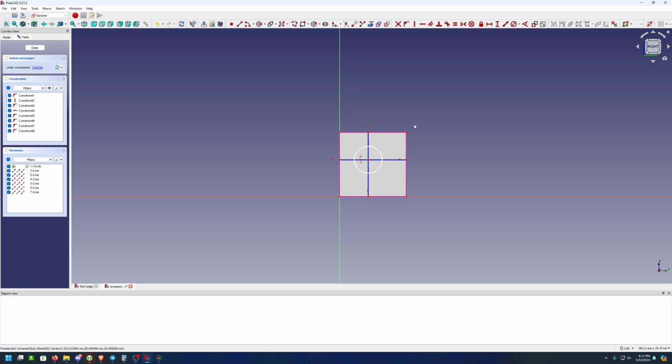I was just kind of guessing. I was like, okay, well, this looks like I'm against this line. And it's just not the right way of doing it. Honestly, if you're doing it right, your sketch will be fully constrained, unless there's a really good reason not to. Sometimes the constraints or the dependencies get a little twisted, and it's good to leave some room there. But I don't know, 9 times out of 10, 95 out of 100, you're going to want to be fully constrained. So, oh, wrong one.